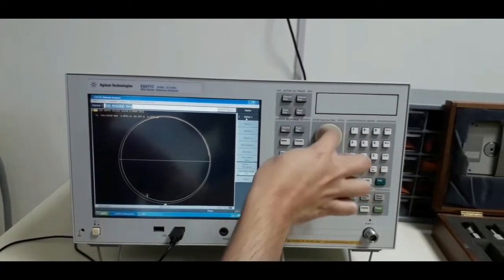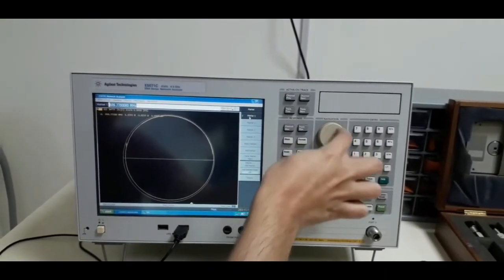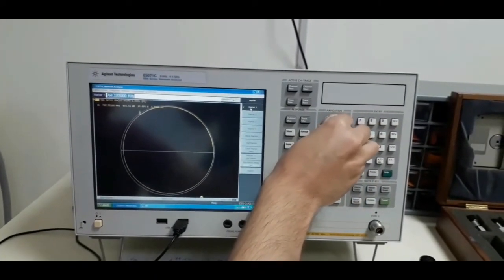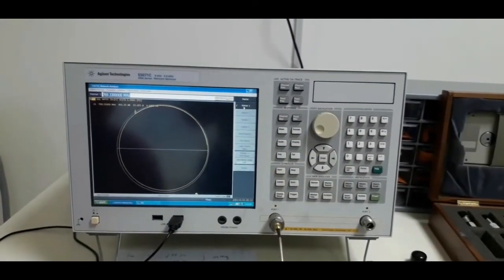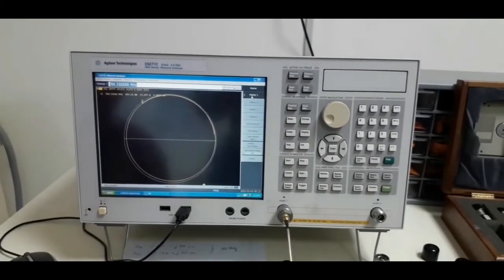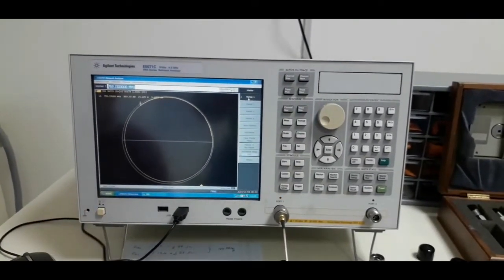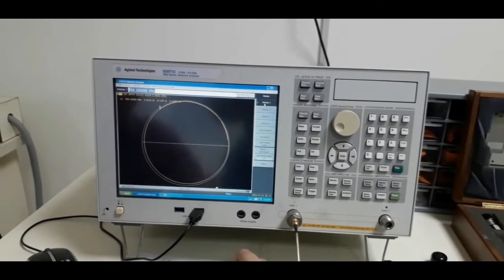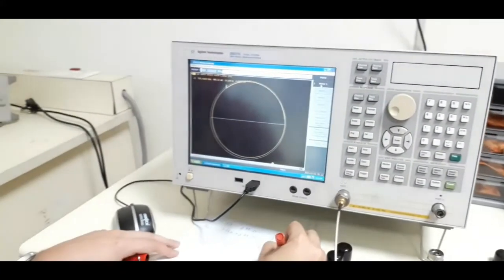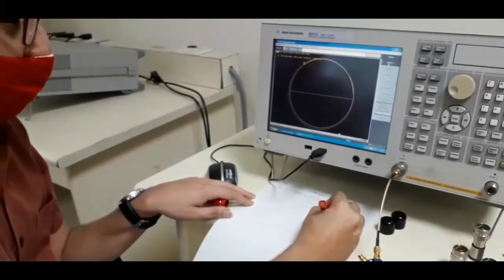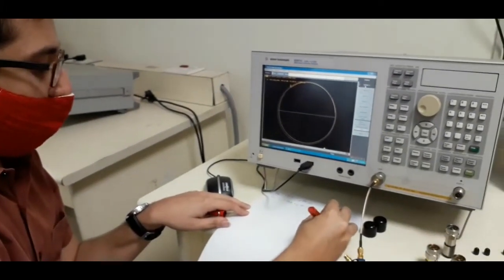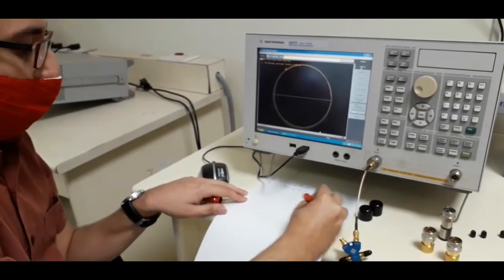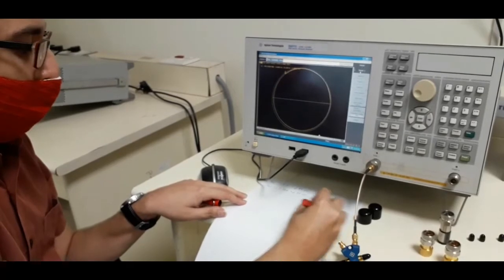You can see the marker is moving and I am now coming back to the same point for a different frequency. So roughly it is about here. At 769 megahertz, it is the point after 100 megahertz at which the impedance is repeating. So if I say F1 is 100 megahertz, then F2 is 769 megahertz, and these are impedance repeat frequencies.